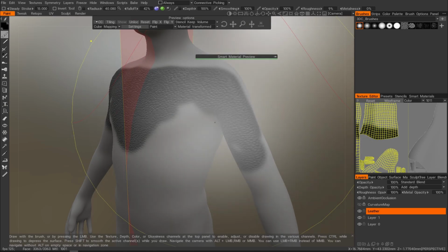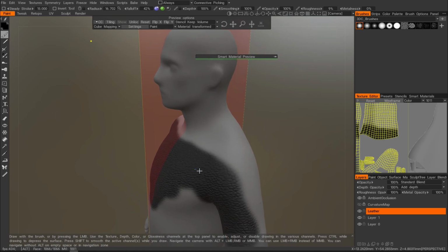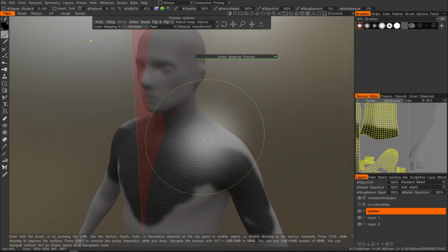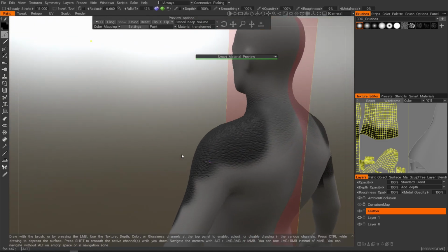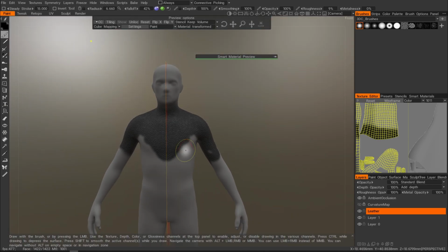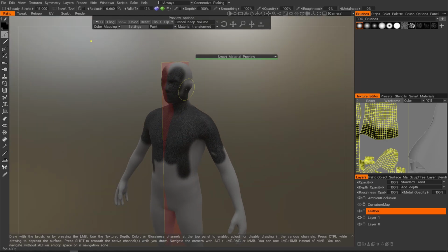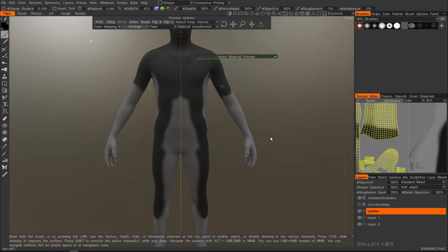So far I don't know how things are going in Substance Painter, but Substance Painter, being a game software, added UDIM quite recently, and it has a problem because you need to paint only on a separate UDIM and then change the layer and paint. You don't have to care about it like in 3D-Coat, where you just paint on all UDIMs.